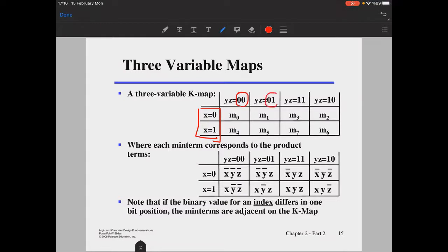So the thing is, be careful. 0, 0, 0, 1. Be careful. This one is, because it's gray coding, it should be 1, 1 instead of 1, 0, and you put your 1, 0 here. See, you just need to be careful about this one, but don't worry, you will get used to it as you use them often enough while solving questions.